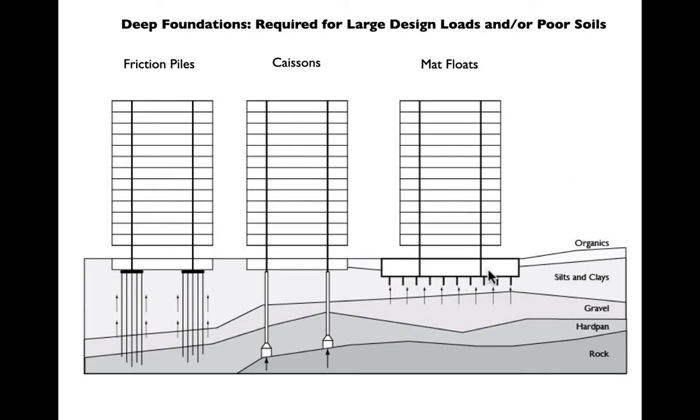to literally float the building, to make the sum total of the building weights less than the weight of the displaced fluid soil, literally floating it using Archimedean principles. Pretty rare, but possible. And again, the worse the soil, the more fluid the soil, the more likely this is to actually work, right? Because it's going to behave more and more like a boat and less like a spread footing.